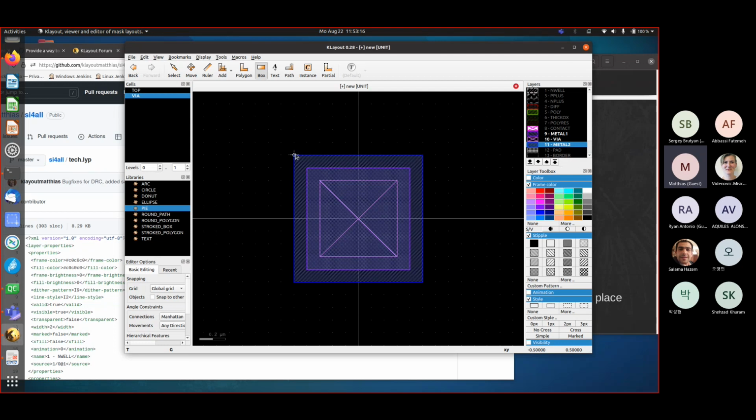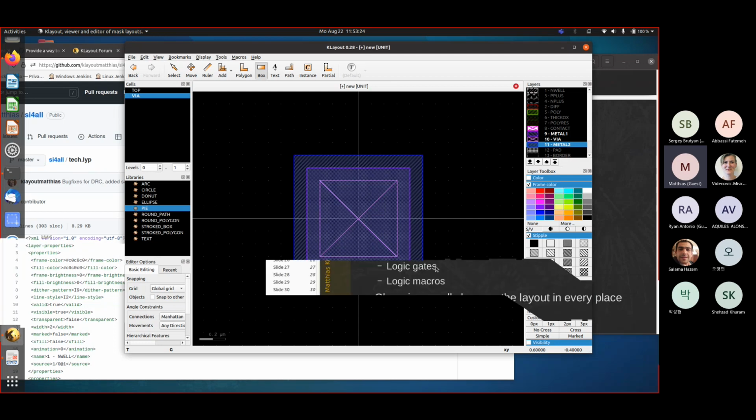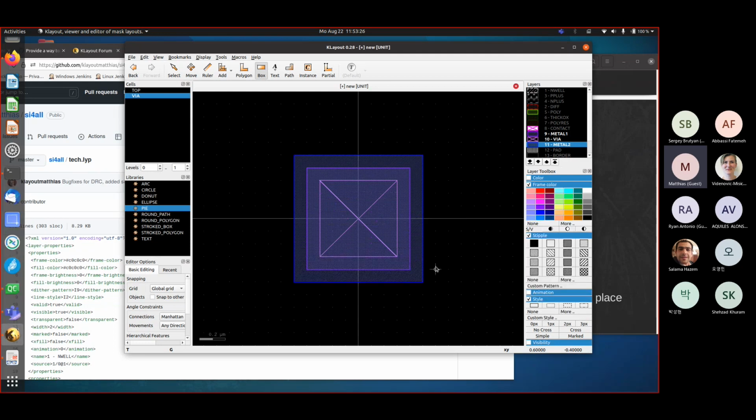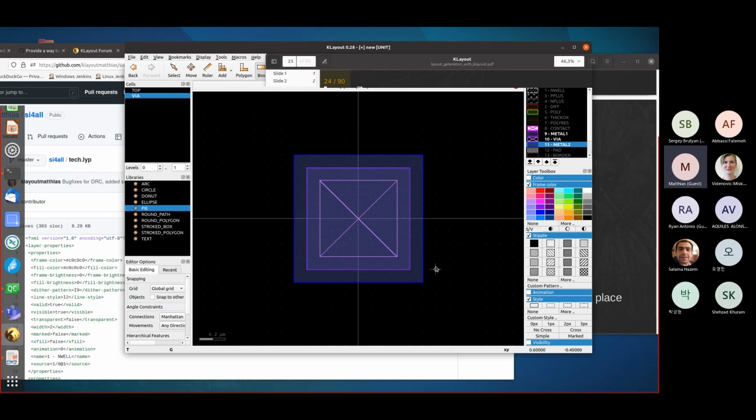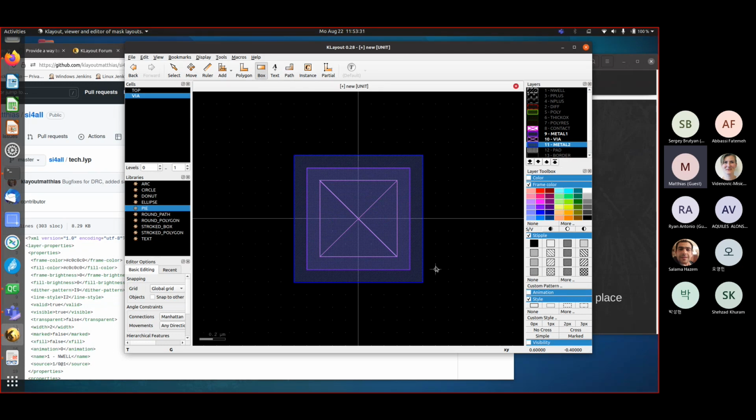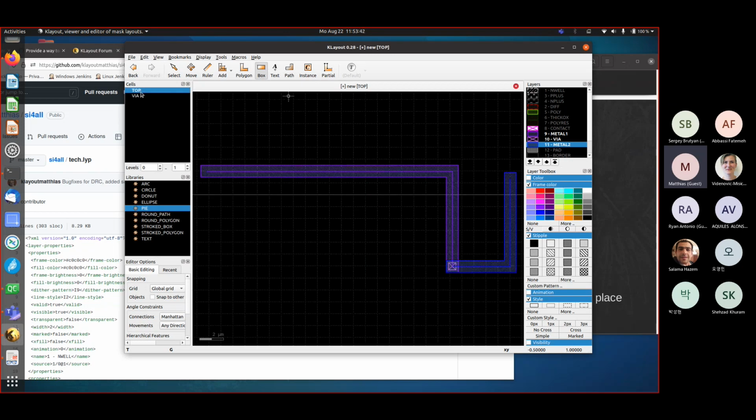Here is -.5, +.5 here, and so on. The reason why I have drawn it symmetrically is that the center, the origin of a cell, plays a certain role. This is specifically the position where you place a cell later. So when I put a cell somewhere, I always specify the location of the origin of the cell. This is important when you code layout later.